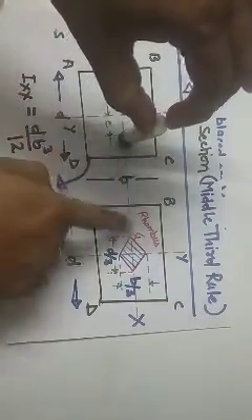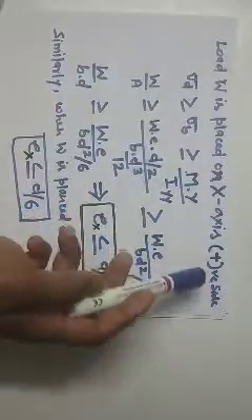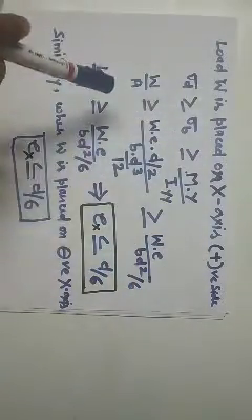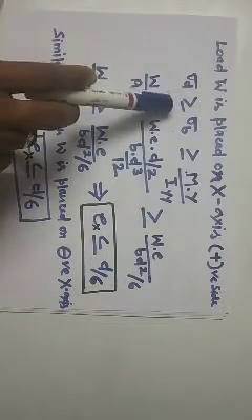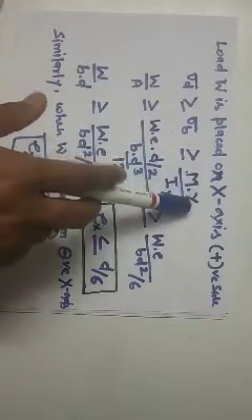So the load is on the positive x-axis at distance e. Clear? So when load W is placed on the x-axis, that is on the positive side, then for the condition of no tension, sigma_d is greater than or equal to sigma_b. Clear? And put the value of M_Y.